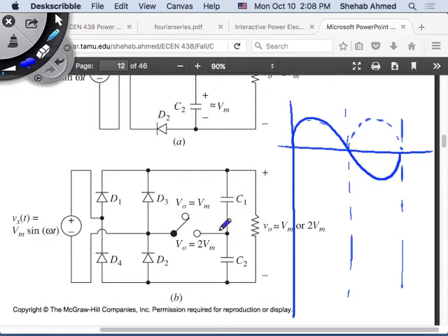Just because I put two capacitors in series, what is two capacitors in series? They have an equivalent capacitance and that's it. So if I needed a certain capacitor value before to get a certain ripple in the full wave rectifier, here I need half the capacitance, right? Capacitors in series are like resistors in parallel. So yes, you need double the capacitance in this case. Thank you.